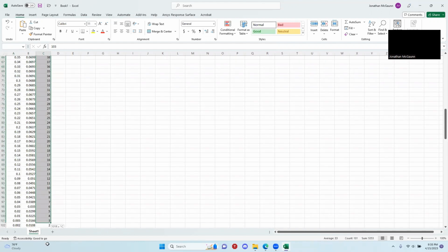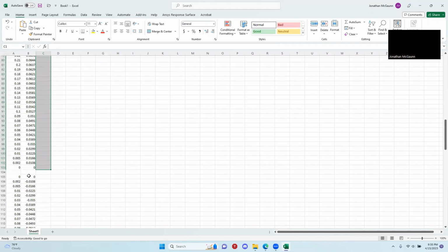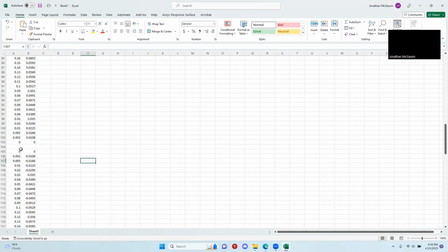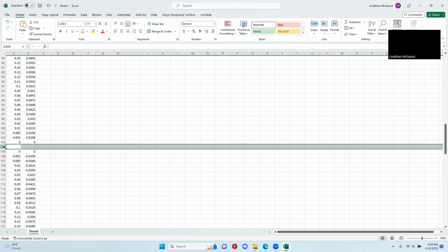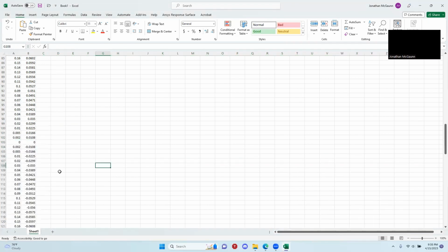So again, not all Airfoil Tools coordinates are like this. I know some of the NACA ones have been adjusted, but some of the more niche ones need to be adjusted properly. So make sure you take out any of these weird gaps as well. It needs to be smooth, and any repetitive points like this and origin are at the end. So now we have a nice smooth curve going from one side of the airfoil to the other with no discontinuities.